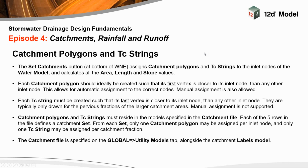What really takes most of the time in all of this is the catchment polygons and potentially the TC strings. The TC strings are a little bit quicker and you don't need to use them quite as often. But in order to allocate your polygons as catchment areas, you use the Set Catchments button.